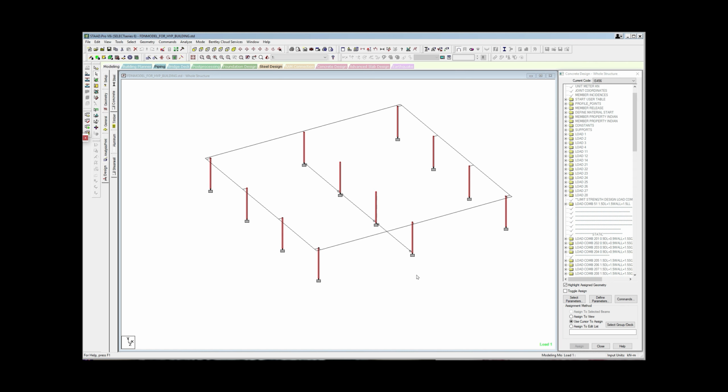We can detail these beams in both ways, as ordinary frame as well, but at times many structural engineers might look for seismic detailing of these pedestals and the plinth beams.